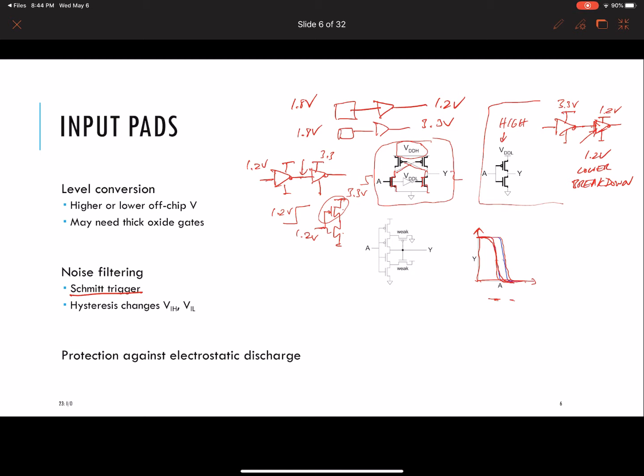They do that, and this is one particular approach, by putting a weak PMOS and a weak NMOS here, and doing what you said you really don't want to do, which is try to get the PMOS to pass a ground. But you're not really trying to pass a logic value. You're trying to just make it harder for this point to switch. Notice if you have a low here, this PMOS is on, and it's going to try to keep this point at ground or close to a low value, and it's going to fight with you a little bit, but not too much. It's just going to push the switching threshold of the buffer in the direction you'd like, to give you some hysteresis.